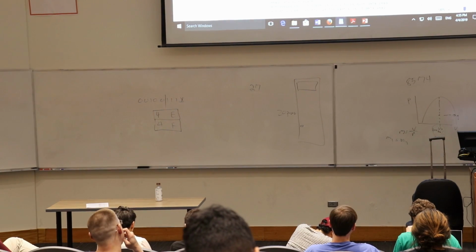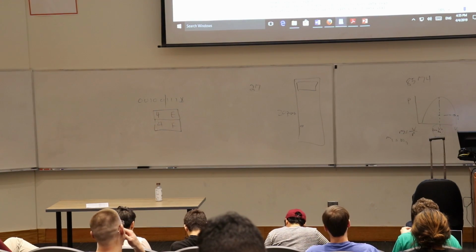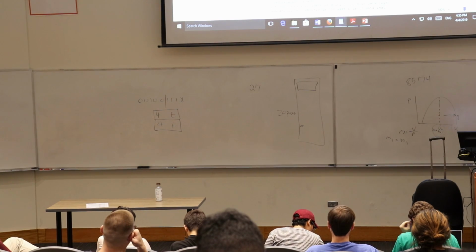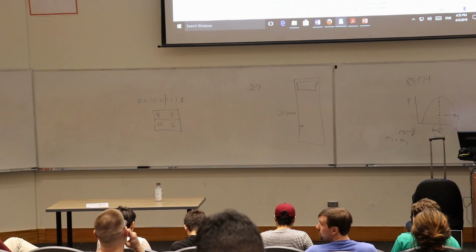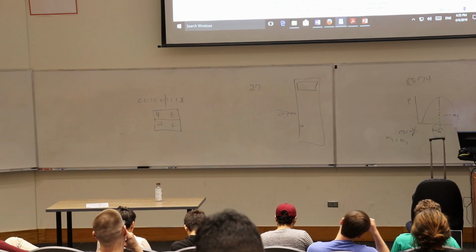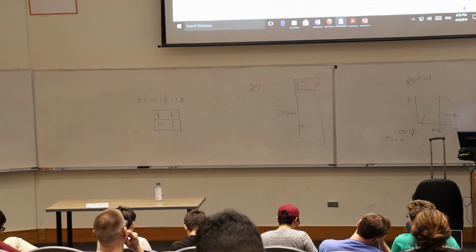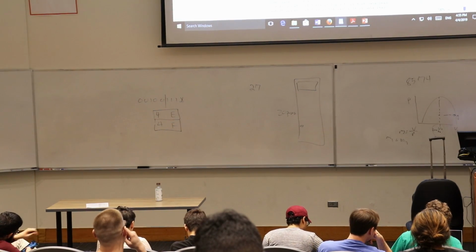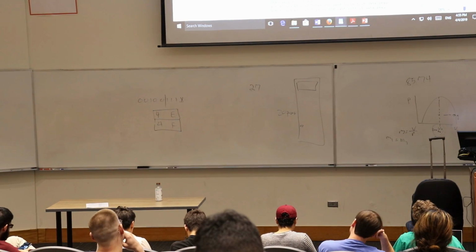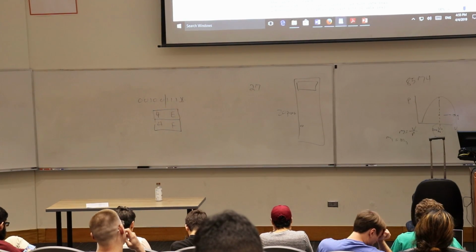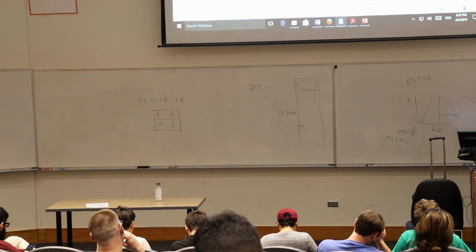Okay, so before you do anything, you have to send out this address, and that's so you can tell which slave needs to respond. All the slaves that are out there are listening, and they're checking their built-in hardwired addresses against the address you're sending out.